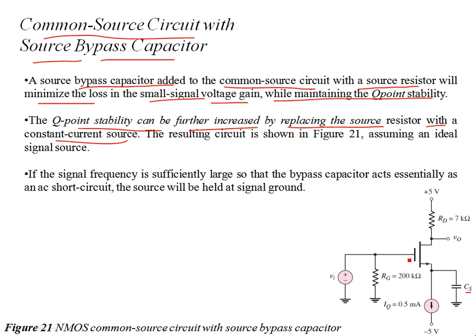In actual IC MOSFET circuits, you might have an enhancement type NMOS device over here, which is modeling the RS resistor. But again, for the current source, you have the NMOS transistors over here. For the purpose of analysis, we are considering these resistances, but even these resistances are being modeled by NMOS devices. Similarly, this current biasing source is also based on an NMOS device in CMOS IC circuits.